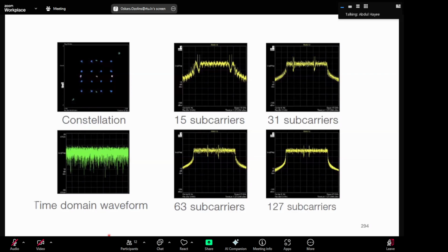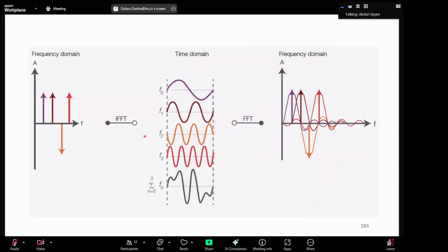If you go back to this slide, yes, here, for OFDM. If we look at the frequency domain, each interval is crossing at the zero points, so it doesn't cause an inter-symbol interference problem in the transmission system. That is why we use the sinc function.